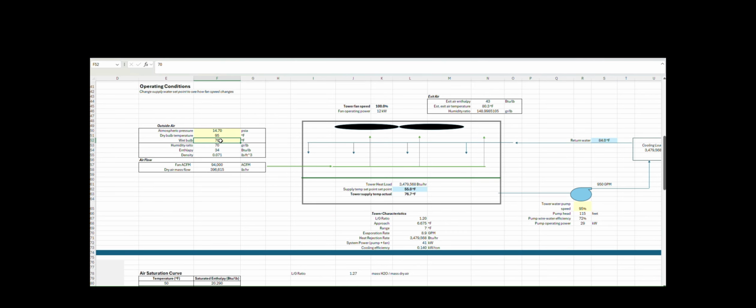So that's our limiting factor. If we're going to do some controls modifications on this cooling tower, instead of running this thing at 100% all the time, you can make this a little more intelligent and say, all right, let's look at our outside wet bulb temperature. It's 70. I know I'm never going to get 70 plus my design approach. So let's try to make 77-degree water.